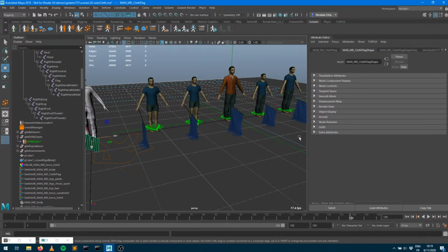That really makes sense if you've got something where you just need to specify which vertices are going to be cloth and which are not, and the rest of the cloth is going to be pretty similar in terms of behavior. That means all the vertices here have the same behavior for the simulation. You don't have individual control on each vertex to specify different properties here. So let's say you need to have this control because you need to do something more advanced. What's the way to tackle that?